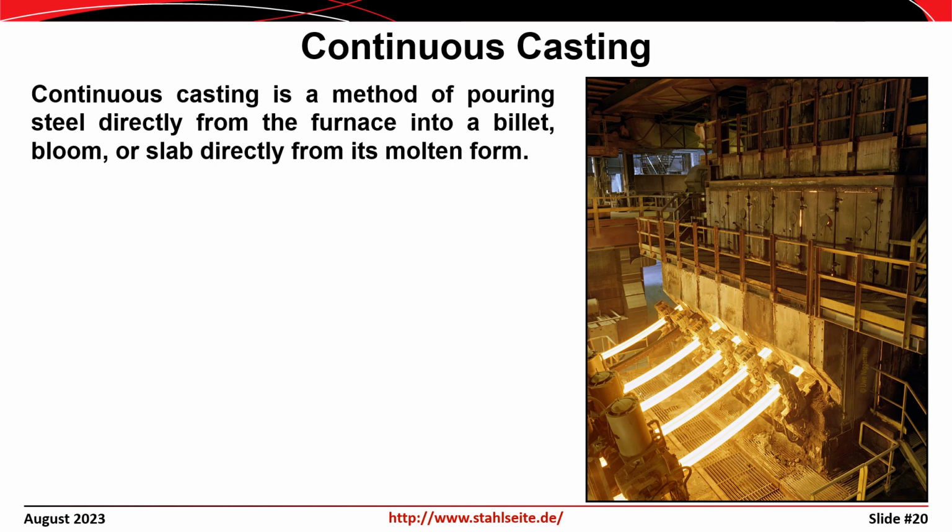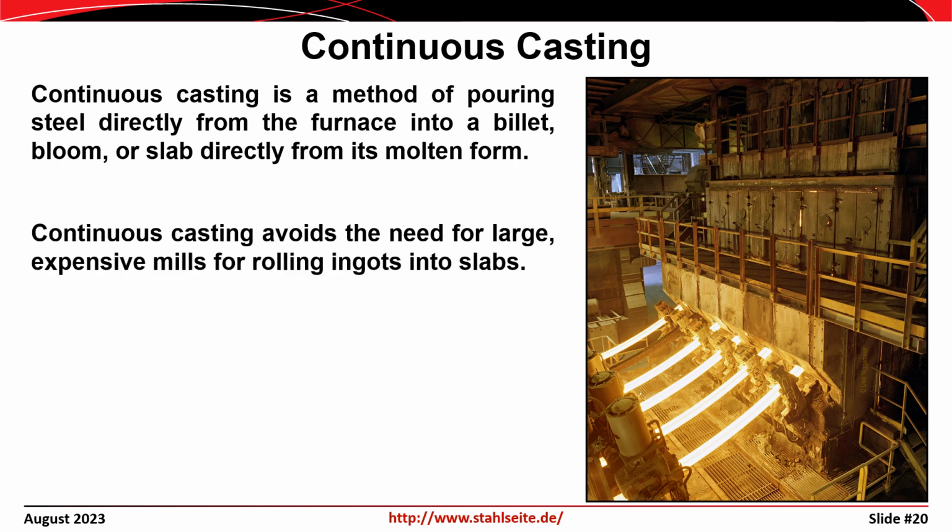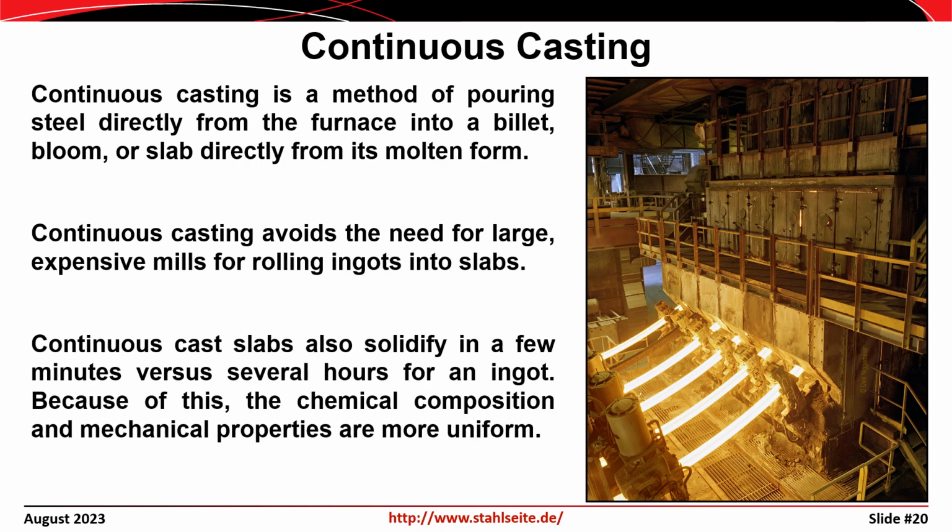All right, now the alternative to casting or teeming ingots, letting them solidify and then reheating them before they're finished, is to go directly from the molten steel into a continuous caster so that you don't have to expend the energy to reheat the steel. So this picture here shows a continuous casting operation where molten steel comes in from the top of this machine or this process and comes out through the bottom, solidified into what looks like either a bloom or a billet.